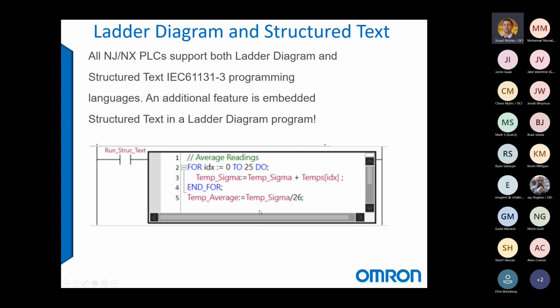So personally, I prefer to work in ladder logic, but there often come opportunities where you need to use structured text to make your life a lot easier. So, operations on arrays, equations where the order of operations is important, that sort of thing. So we can actually embed structured text in our ladder logic and conditionally execute it with ladder logic conditions.